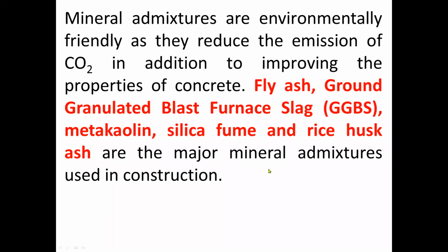Mineral admixtures are environmentally friendly as they reduce the emission of carbon dioxide, in addition to improving the properties of concrete. Fly ash, ground granulated blast furnace slag or GGBS, metakaolin, silica fume, and rice husk ash are the major mineral admixtures used in construction. So I repeat, we have the fly ash, GGBS, metakaolin, silica fume, and rice husk ash.